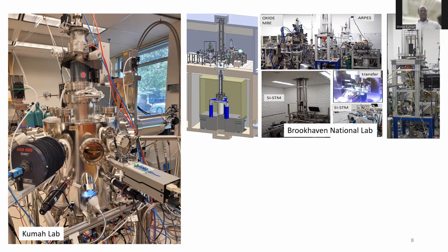Sticking up from the top here is something called a substrate manipulator. What a substrate manipulator does is hold a single crystal substrate, the template on which you want to grow your material. It allows you to heat up and control the temperature of that particular crystal substrate. And controlling the temperature of the substrate allows you to control the epitaxial process when you're trying to grow a material. So even though this system by itself might look a little bit complicated with all the wires going in and out, the operation is relatively simple, and I will again talk about that in some more detail.